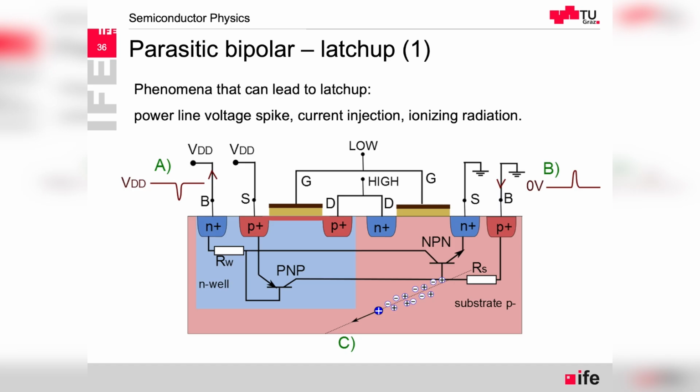So where we have the high power supply and ground both applied, these transistors, which should normally be off, suddenly have the base-emitter of the NPN transistor forward biased. That means we have some current, maybe very small because of the series voltage drop across this resistance. And then some collector current starts flowing.